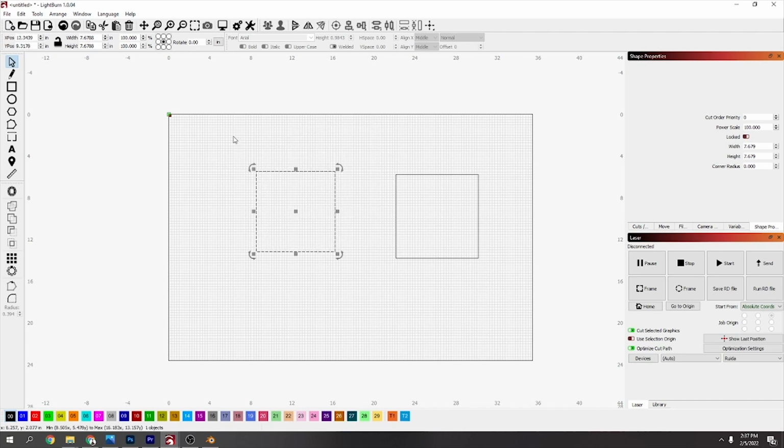To select these, if you drag across from the left to the right, when it's red, if you fit it all in, it'll select it. If you don't fit it all in, if you just missed a bit, it wouldn't. So if you had a load of stuff in the middle that you wanted to cut out, but you didn't want to take the outside box, you could just drag that across. If you drag it from right to left, anything it touches, it will select.